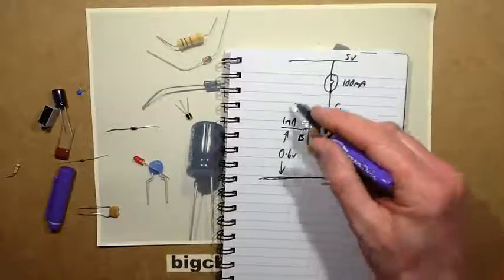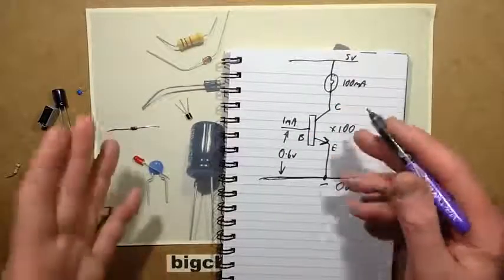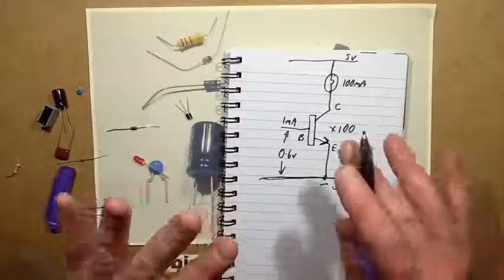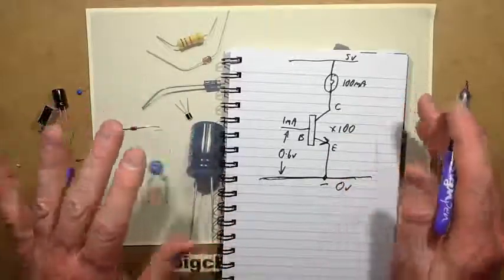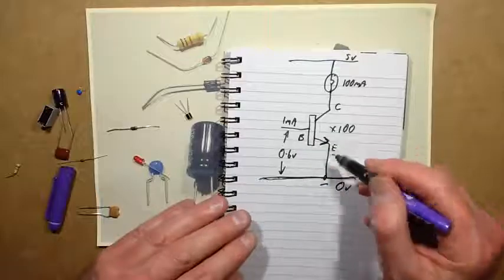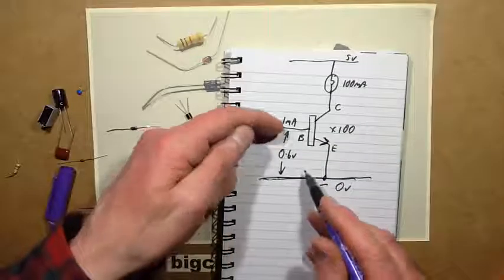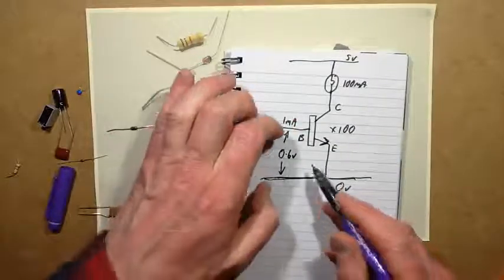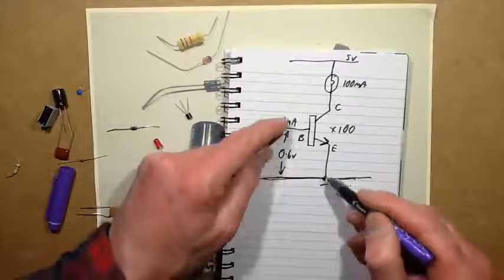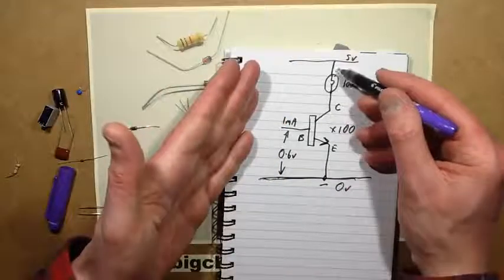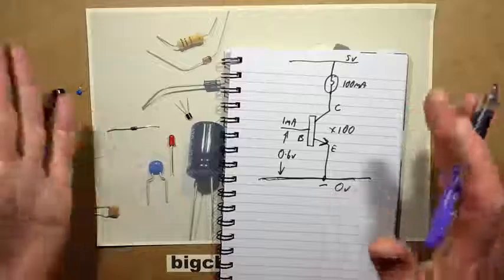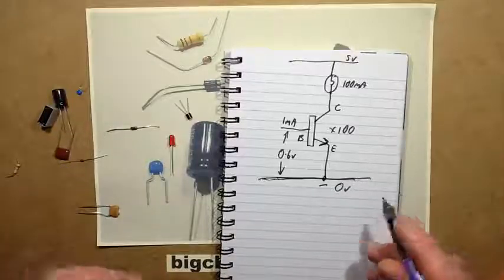You can also use them in other formats, like for voltage and current regulation, things like that. But just knowing the basic operation, that as soon as the base has a certain amount of current going in at roughly 0.6 volts above the emitter, then the collector current will flow. That's all you really need to know, just to get started.